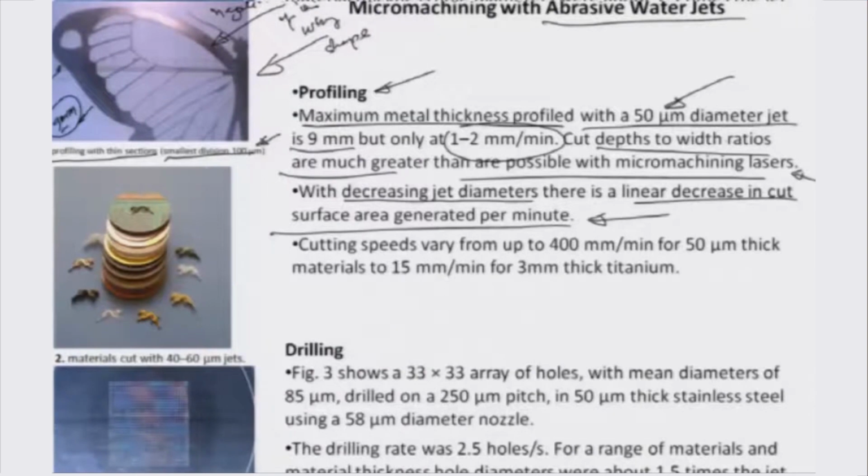On one side you have a thickness of 9 mm, on another side you have this teeny tiny feature here of not more than 100 microns. So, you can think of the high aspect ratio. This cannot be easily obtained on any other machining process except this abrasive water jet. So, that is the power of this process in being able to micro size the parts.